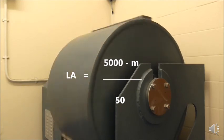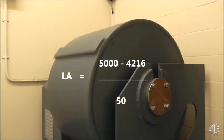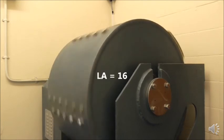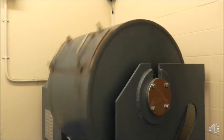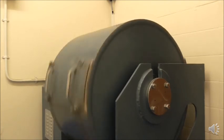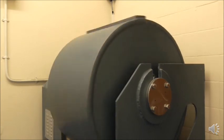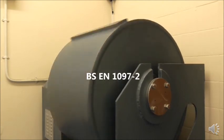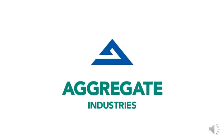So the Los Angeles test is basically just trying to find a ratio. You take the original weight, you minus the final weight, and then you divide it by the original weight again, and then you multiply it by 100 to get a percentage. So the Los Angeles test here is 16%. That means that 16% of the aggregate has turned into dust.